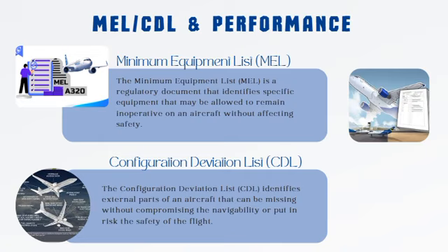However, the CDL will typically include performance penalties associated with missing items, such as increased drag or reduced fuel efficiency. Each CDL item lists the permissible deviation, any required compensatory measures, for example increasing the fuel load, and any performance adjustment.